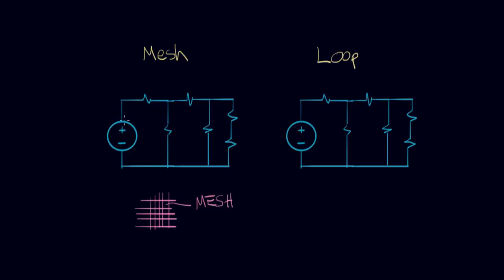That's what that word comes from. So we're going to find the meshes of our circuit. And what we look for, here's the branches. And the mesh is a kind of a loop that fills up this open space. This circuit has one mesh, two mesh, three meshes. That's how that looks. To draw a mesh, you start on a node. You go through elements until you come back to where you started. That's how we did those three. And they fill the open windows of the circuit. So this circuit has three meshes.